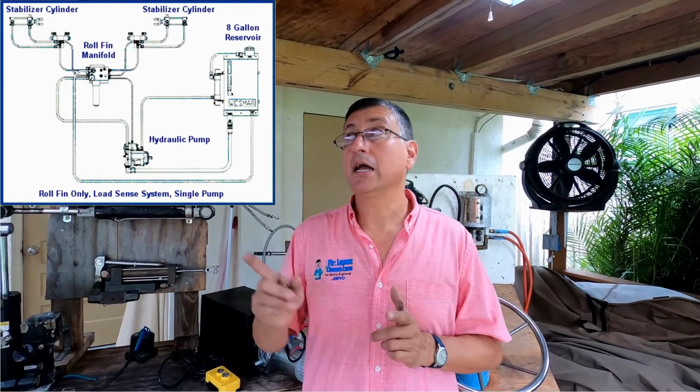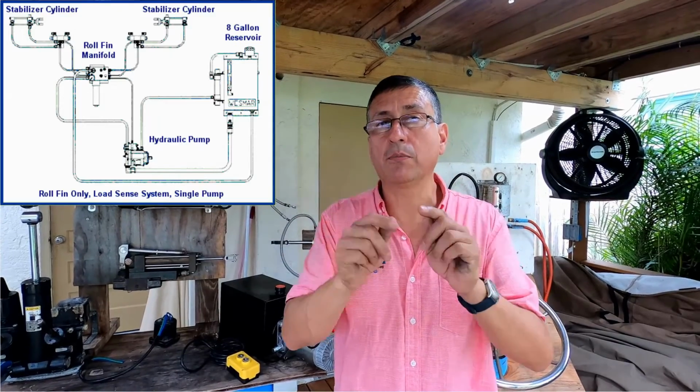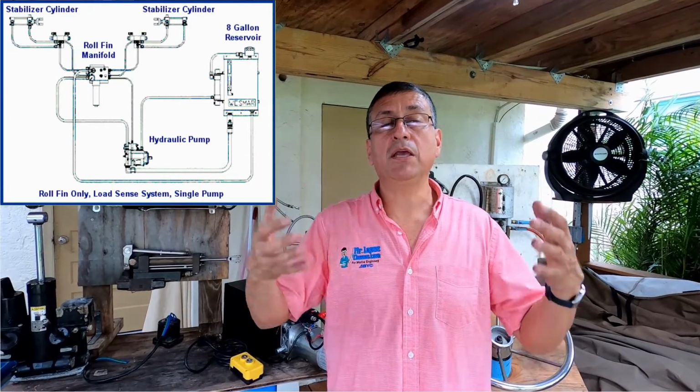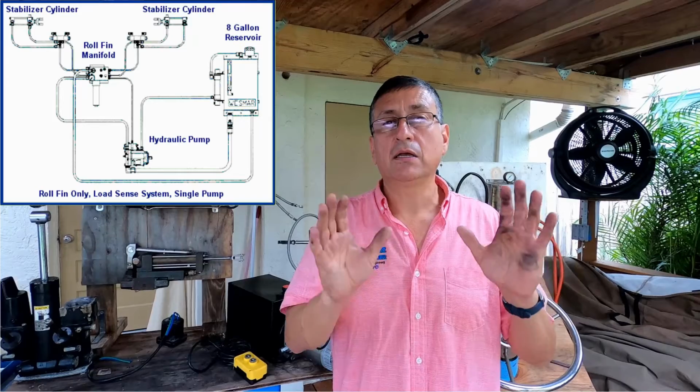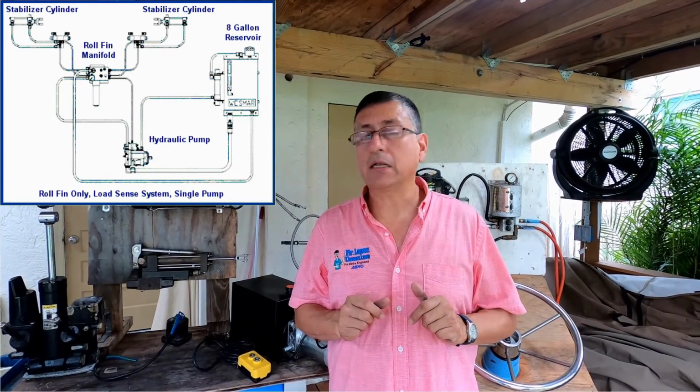Don't forget that in all of those systems you need to be clear about the hydraulic schematic of your particular boat. Keep the schematic in your hand, keep it in your office, exactly the same as the wiring diagram, you remember? Exactly the same.